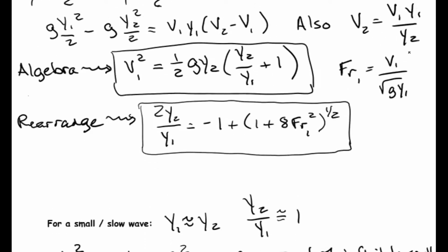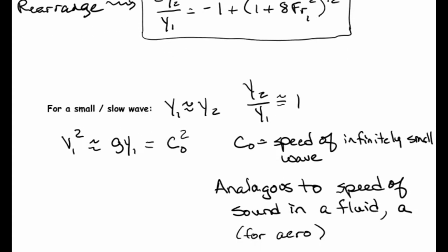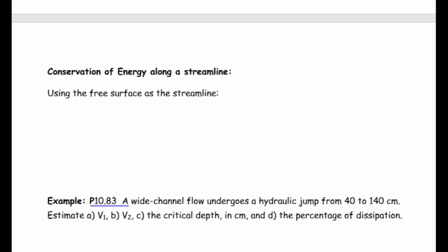We had from above, conservation of mass gave us an equation for V2 in terms of V1 and our y's. So let's finally do conservation of energy. So the losses, we're ignoring frictional losses, but there are still losses. They're kind of like minor losses. We are going to call them HF in our equation, but they're really kind of like minor losses.